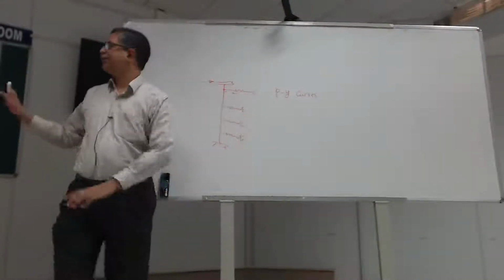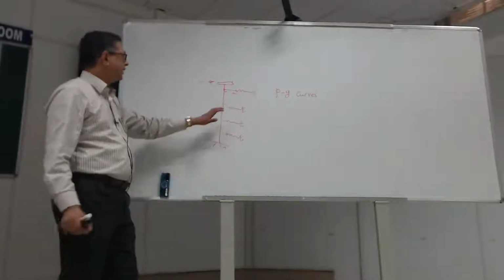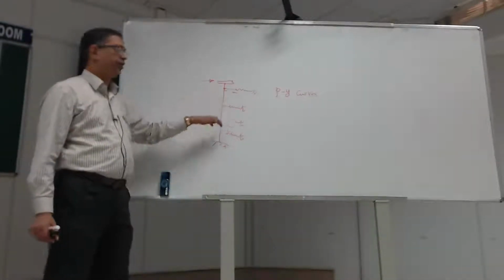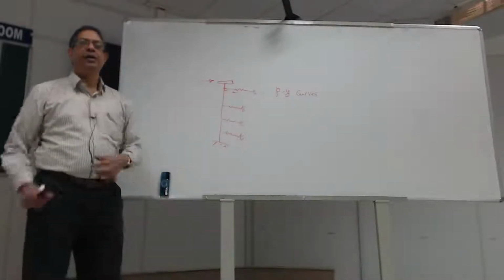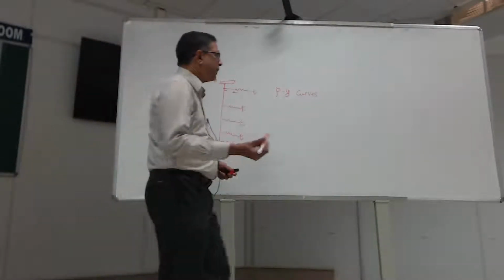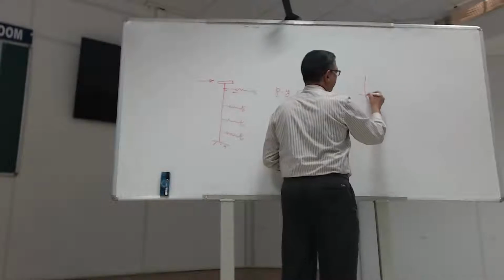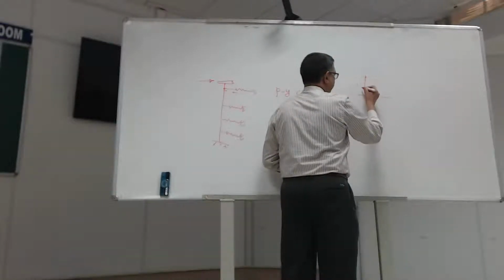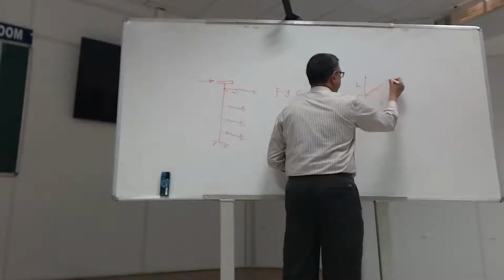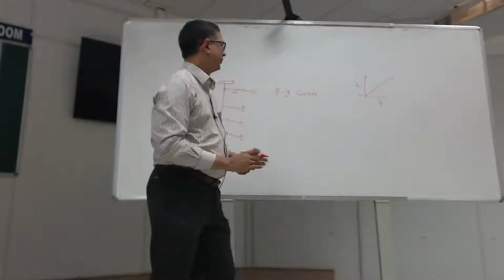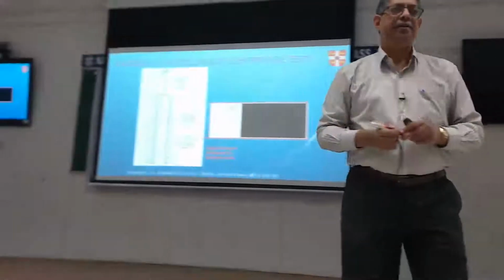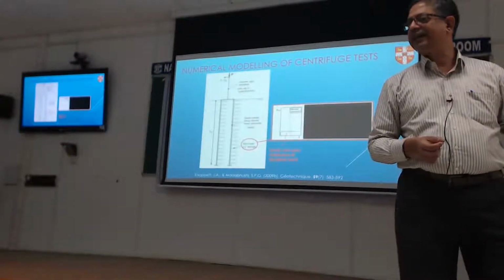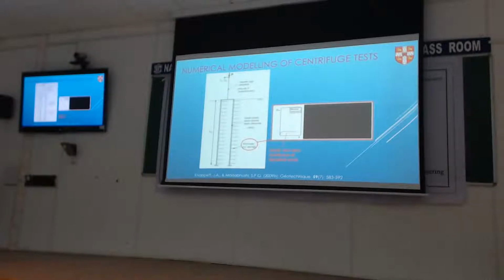So we can forget the soil completely and replace it with these P-Y springs, as many nodes as you want, and you can prescribe what the spring characteristics are. Now, the springs could be simple linear springs. So the more deflection I get horizontally, the more force it generates, and it just increases linearly. Now, clearly, this would be equivalent to doing an elastic analysis.